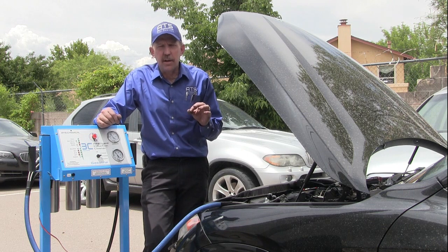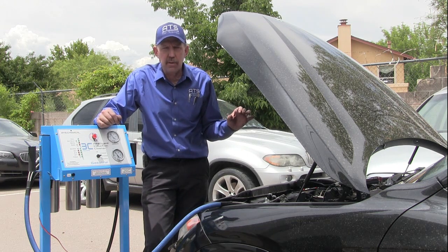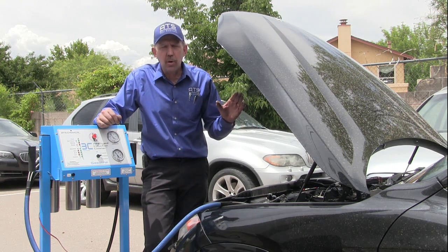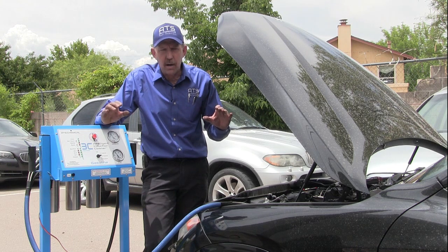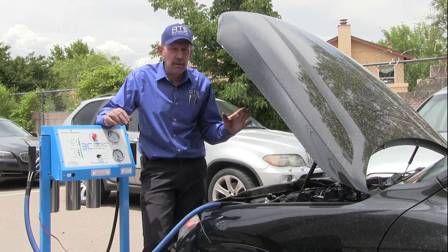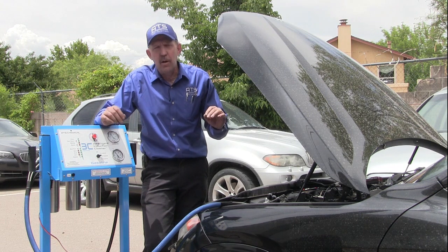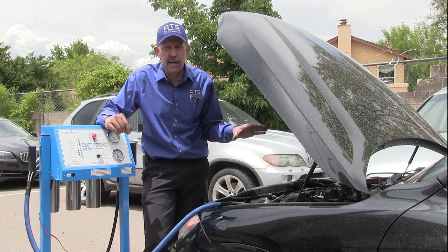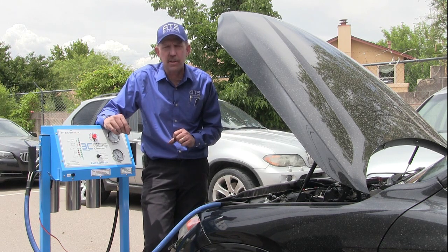If you start to hear light pre-ignition during the wide open throttle, back out right away. Now slowly roll back into the throttle, and if you hear any audible pre-ignition, back out, and go ahead and apply it again. We want to do this very slow roll-in until we clear any chemical puddling from the induction system.